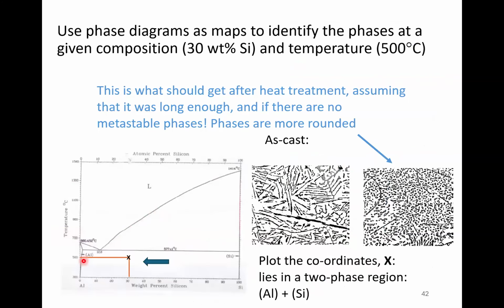Okay, and then here's aluminium silicon, very good for alloy wheels. There's a few other things put in there. If you cast this thing, say we're over on this side, you're going to get big needles of silicon, okay? And silicon is brittle, and it can crack very easily, it can jump across a little neck, carry on cracking, jump across a little neck, carry on cracking, and soon this whole thing has got a crack running through it. You really don't want that.